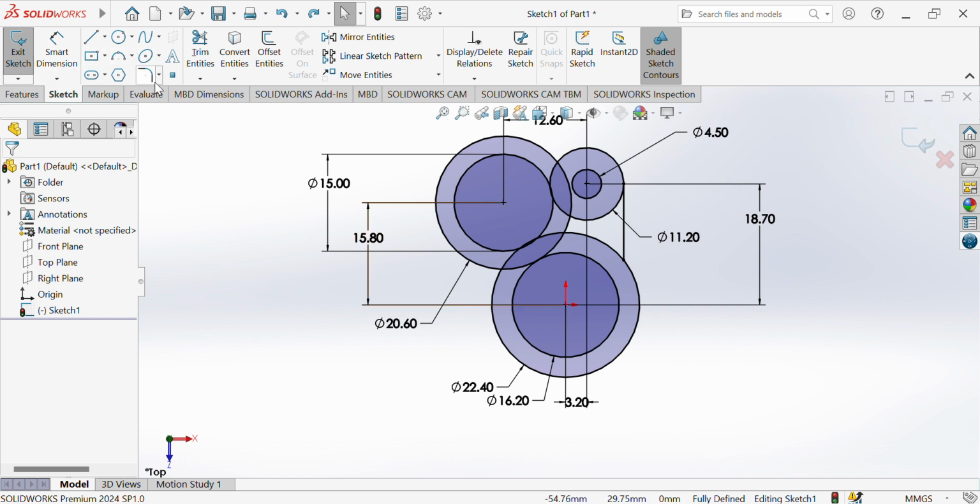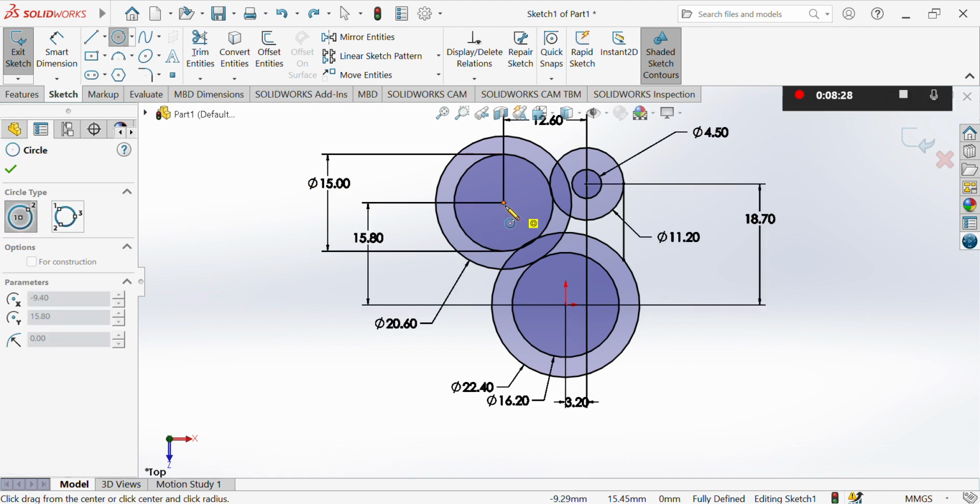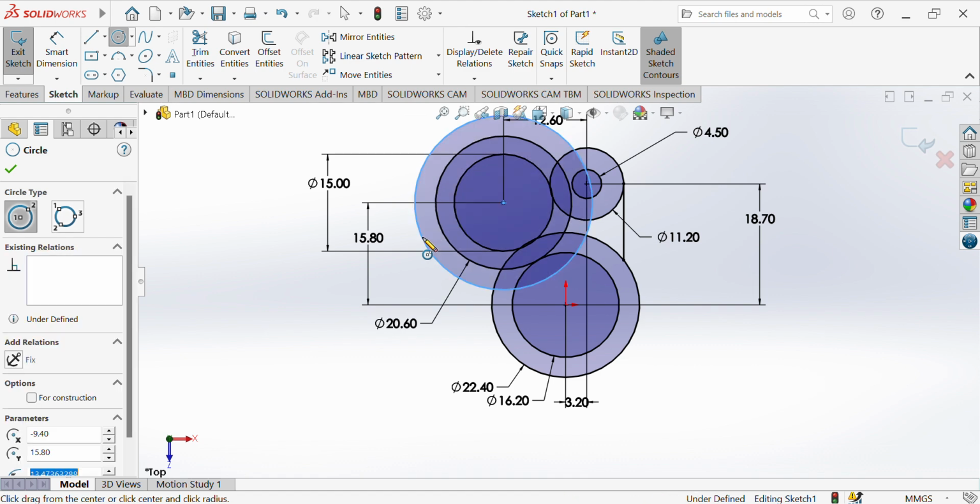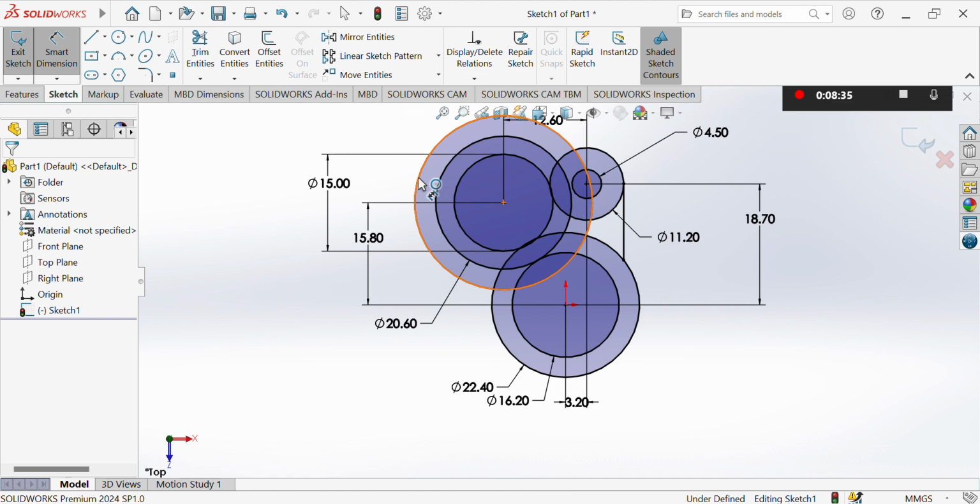So remember that I taught you a method of internal tangents, so you can use that here. Just add the radius of the curve to the radius of the outer ones. So if you want to do from here and this one, the radius of this outer one, what is it? The radius is 10.3, so plus 3, we just take our circle to 10.3 plus 3 is 13.3 times 2, 26.6. So small dimension needs to be 26.6.